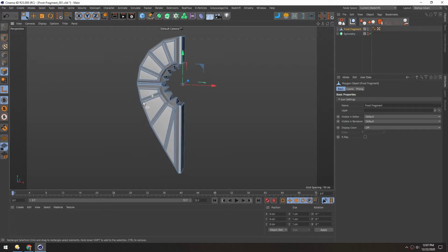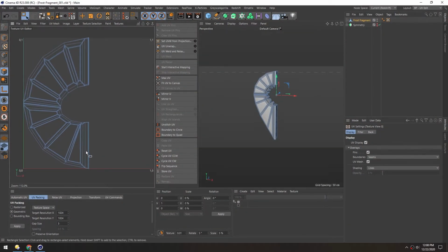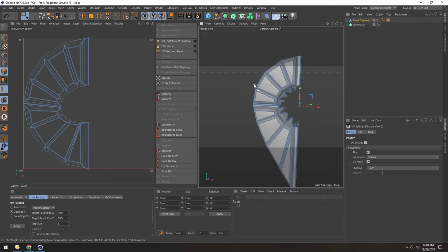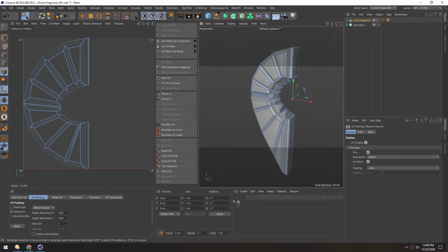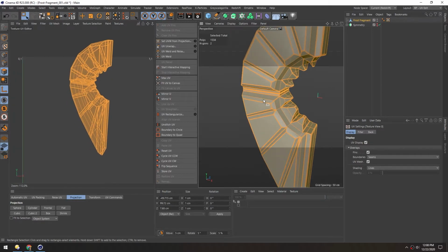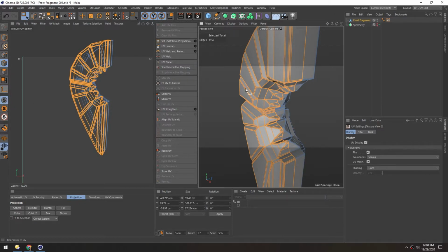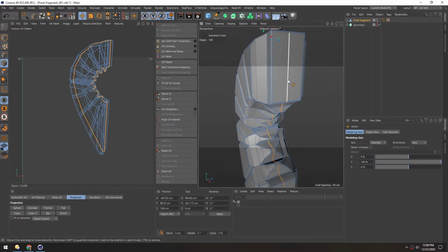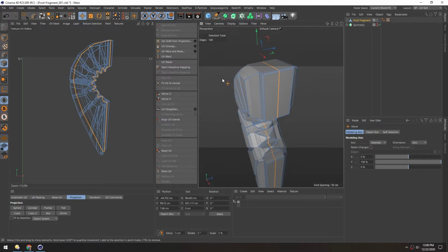And the UVs are going to be really bad, so let's go to BP UV Edit. And you can see it kind of has the shape, but it's not taking into account the back and the front faces, and all these middle pieces look like they're not even there, so we need to basically start over. So under Projection, let's just do Frontal, just to get a base level here. And because the front and the back are the same, we can select this edge. I'm going to turn off Enable Axis here. And just double clicking this edge should select the whole ring, or the whole edge loop. And now let's UV unwrap that.